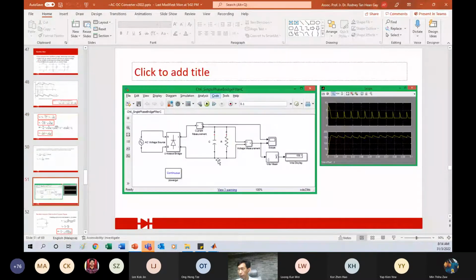This is one of the classic examples I have shown last week. If we put a capacitor, of course, you will be able to smooth the output DC. However, it will create another problem, which gives you what we call non-linear currents. That means the voltage and the current are not drawn in the same way. You can see this in the waveform, especially when you place this capacitor there.